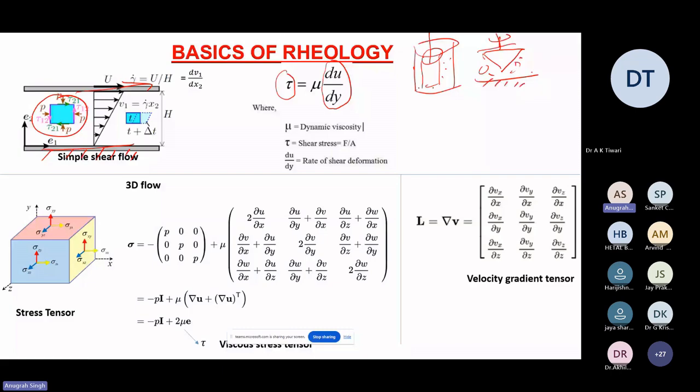And from the torque you can know the stresses, or you have a parallel plate where the top plate is rotating at a certain rate and the bottom is stationary, and you put your material between the two plates. So all these are examples, and the gaps are such that the shear rate is constant. So all these are examples of planar shear, right? So you have one component of velocity gradient and you measure the stresses, and the proportionality constant is, let's say, viscosity. So viscosity is just one rheological property, dynamic viscosity.